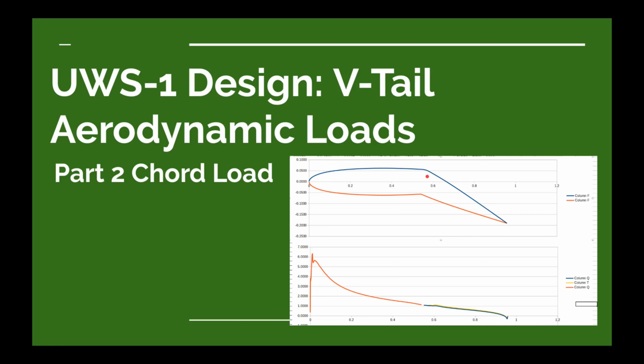And don't forget that the calculation that we're going to do here for the chord load won't be quite right. It'll be good enough for this first cut at determining the chord load, but we actually have an elliptical nose on our rudder, and the software we are going to be using basically sticks in a plain flap without a gap. We're going to have a gap, so our actual behavior will be a little bit different, but for this first cut at our design, it's good enough. And just to give you a little feeling for where we're heading, this is the chord load distribution.